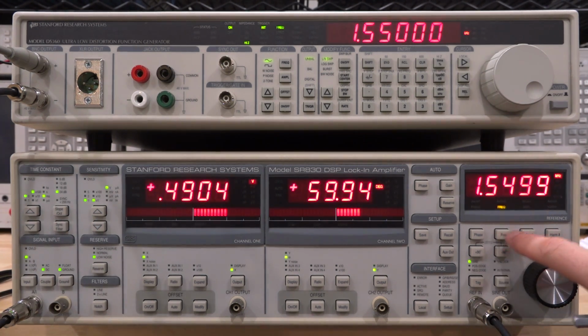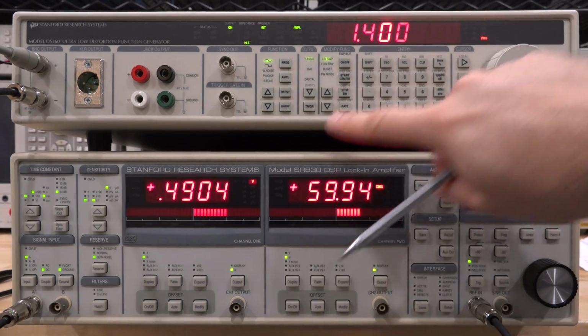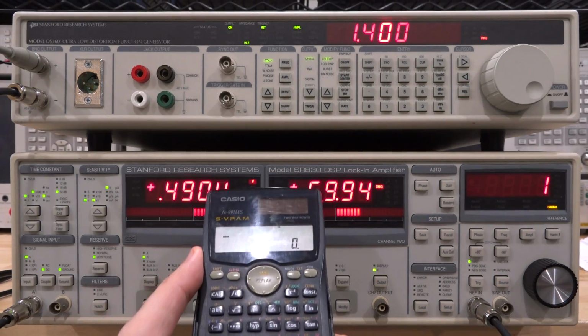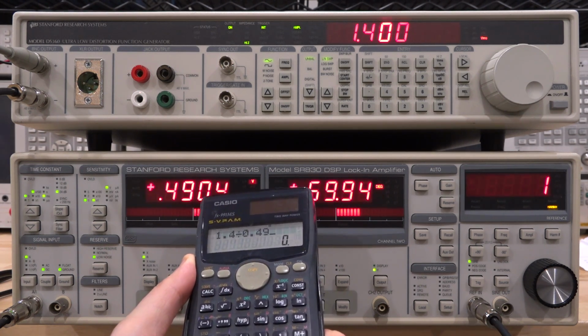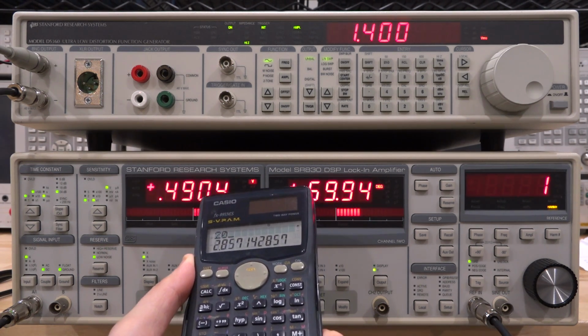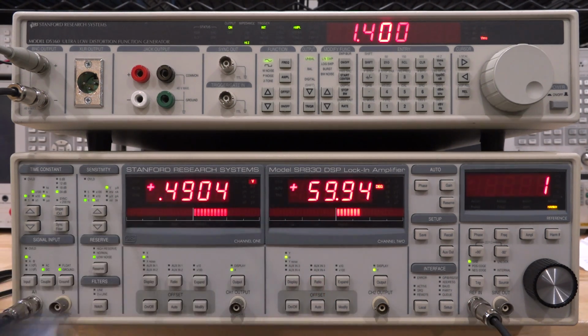And if you go to frequency, you can see that we now are looking at the frequency of 1.5 kilohertz and the first harmonic. Now we can make this division because the amplitude hasn't changed and see if that number is correct. We can do that again. So we have 1.4 divided by 0.49. And we do 20 times log 10 of that. And look at that, 9.1 dB, almost exactly 9. So everything is correct. Now we can, with confidence, make our measurement.